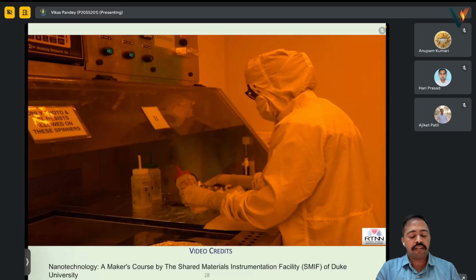In general, directly gold cannot be coated over silicon. So generally chromium or titanium is used below it, or we have seen that Ti is coated, then aluminum is coated, in the metallization part. Sometimes this photoresist is fine for gold etchant, it is not getting affected by gold etchant, but it will get affected by chromium etchant.